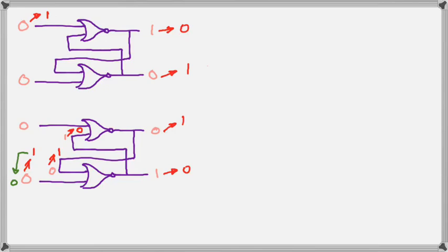If it's gone by too fast, rewind and play it in slow motion. Now what has happened is here, the 1 at the very bottom, after going to a 1, has gone back to a 0, and the pulse is passed. However, that very bottom line has lost control to cause any further change in the flip-flop. So the bottom flip-flop has now assumed the position of the top flip-flop at the beginning.